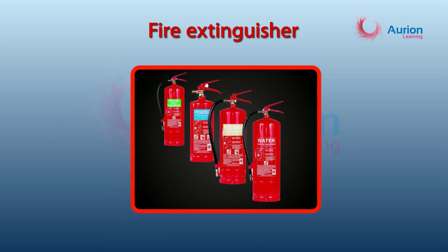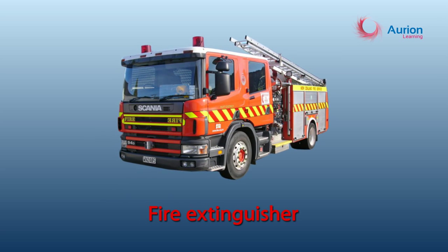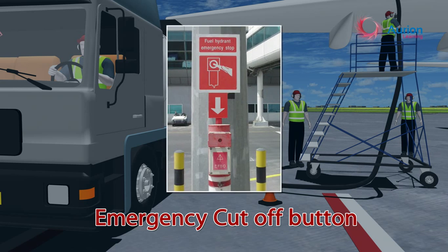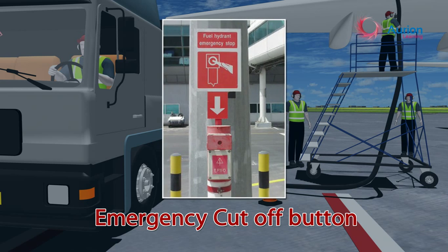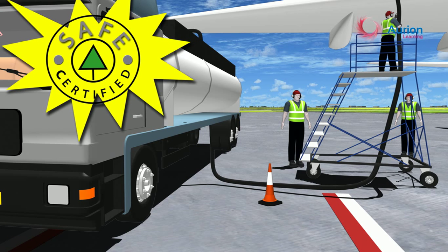Have the correct type of fire extinguisher available. Wear eye protection. If the fueling activity turns into an accident, the fire brigade must be called to any accident involving the fueling vehicle. Find out where the emergency cutoff button is located on the fueling vehicle and/or at the head of stand and switch it off. Remember, subject to the equipment being in good condition and safety procedures being followed, fueling is a safe operation.